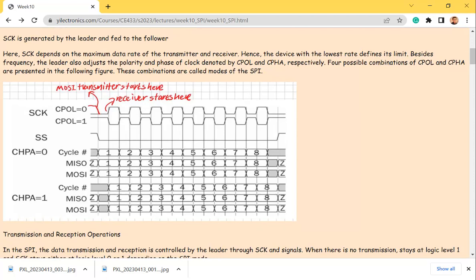So we're going to use SPI because this module has SPI inside. I'm going to give it to you right now. One very quick question: could you see the light sensor? It's a little LED, right? It's a photodiode instead of the LED. It's not emitting, it's receiving and converting the photocurrent into voltage.